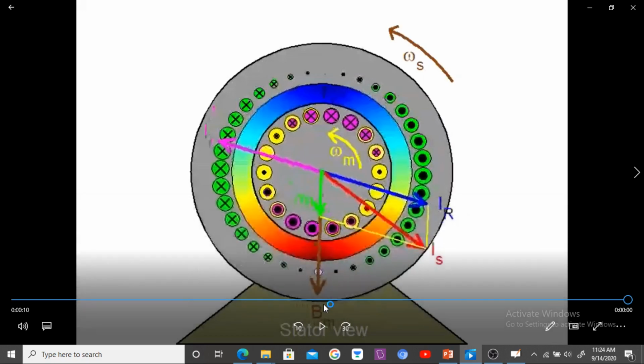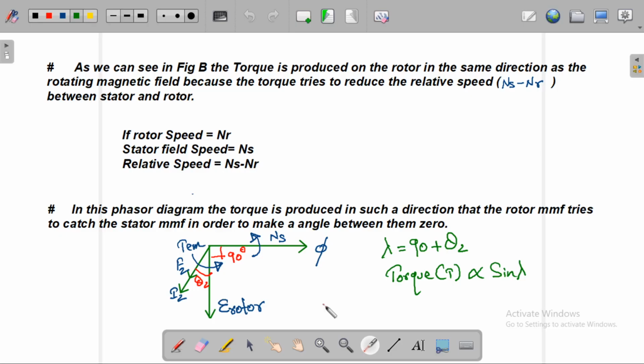Due to the air gap, the entire flux of one winding does not link with the other winding, and there is some leakage flux, which is represented as leakage reactance in the equivalent circuit, and hence the current lags behind the EMF by a certain angle.